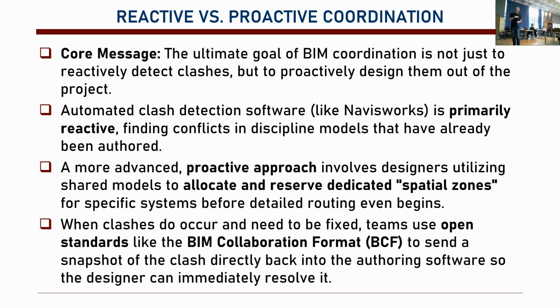So you avoid clashes, and you result in federated models which are clash-free for the studs. Okay, so you want to do that. So this is what we call the proactive approach. Basically, we have shared models, but in these shared models, we also allocate and reserve dedicated spatial zones for specific systems.